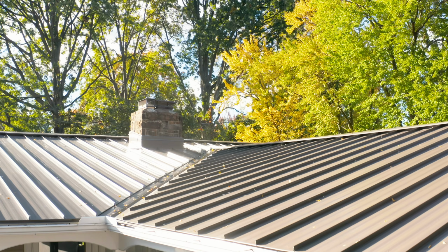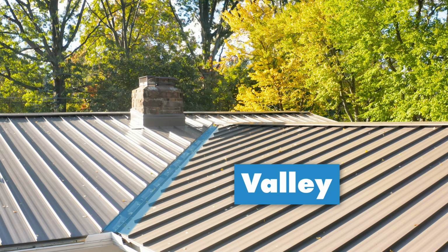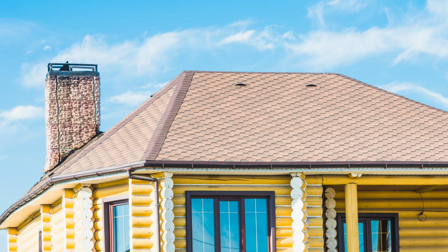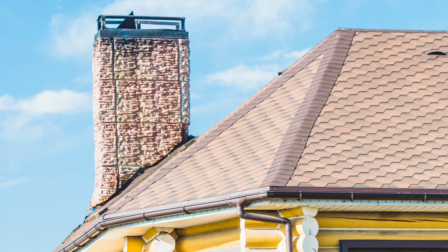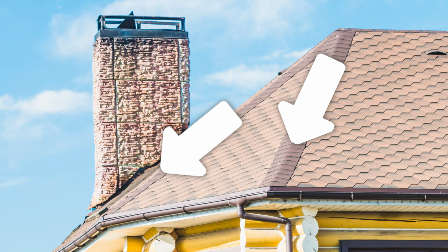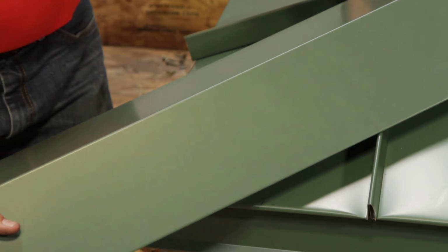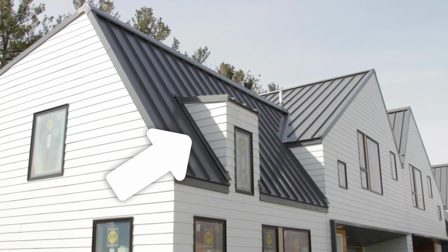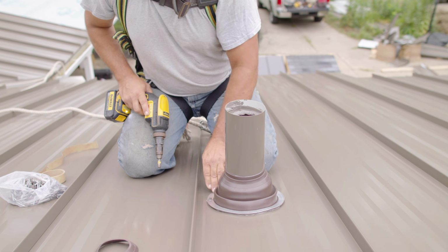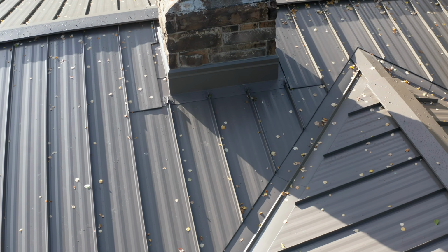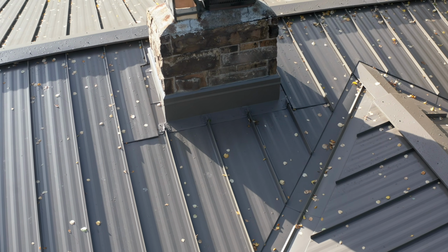Another standard flashing zone is a valley. This is an area where two roof planes meet, and water is intended to drain down the valley off the building. A different roof type is a hip roof. Instead of the roof plane ending at a gable wall, all sides of a hip roof slope downwards towards the walls. Hips are installed similarly to ridges. Some other common flashing zones are head walls and side walls, where a roof plane meets a wall, pipe penetrations, where a rubber pipe boot is often installed, and square penetrations like skylights and chimneys.